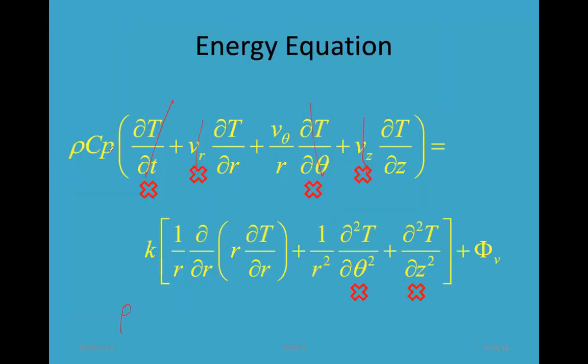So here, tangential flow of an annulus with viscous heat generation. You can use the energy equation. We can delete this one because this is unsteady. Vr is 0. We have V theta, but ∂T/∂θ is also 0. It doesn't spin faster or slower over time. And then we don't have Vz. This is for the tangential one. We don't have this case, so here is the energy equation.